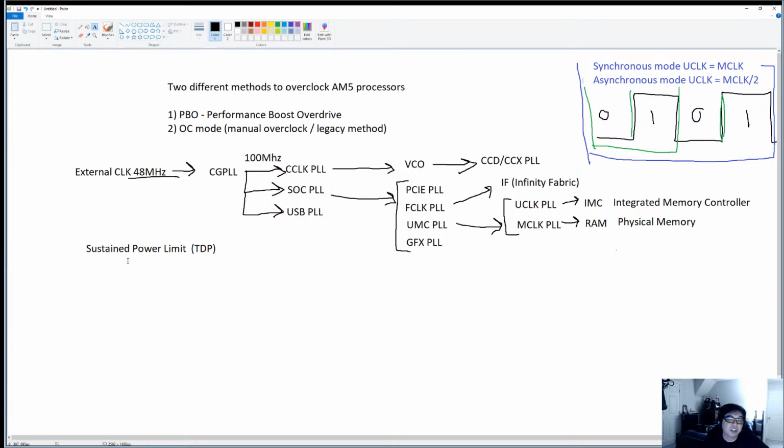So eco mode is a very good safe bet if you want to run on air cooling, for example, and you don't want to deal with 95C, even while doing a full Blender run or Cinebench runs, or overclocking. With overclocking, you're not going to be power limiting yourself, but there is Curve Optimizer for that, which we will talk about in a little bit. But eco mode is definitely a thing for 24/7 operation. It makes the processor behave very similar to the 5950X, while outperforming it in every way imaginable. So there is that as an option.